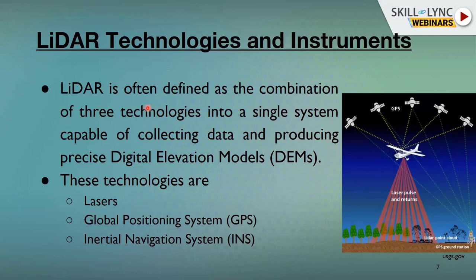You can see there are some GPS in these images. The satellites are there, and the base locations are placed. The base locations communicate with the satellites, and those satellites are integrated with the aircraft, and then the laser pulses come to the ground and are returned back to the aircraft. So this is the general methodology and process working in airborne LiDAR technologies, or mobile LiDAR, or terrestrial LiDAR, whatever. This is how the system works during the data acquisition part.